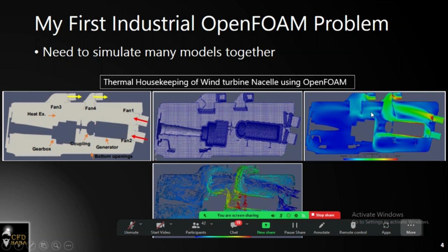So the solution I proposed was that we can extend the length of the fan 4 duct and we can increase the speed of the fan slightly.